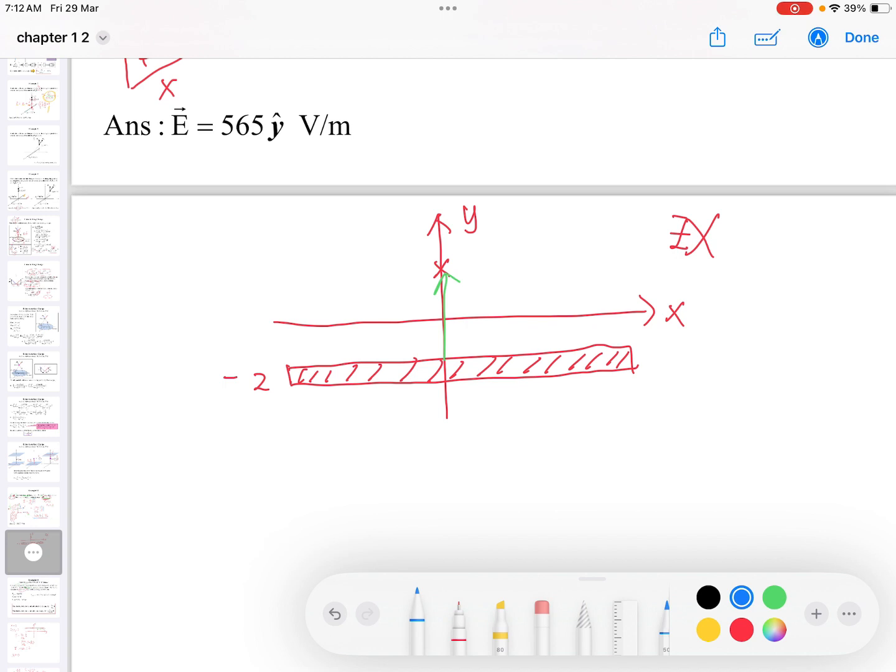Okay, the axis that you must draw is the axis that your plane is located at. So your plane is located at the y-axis. So you can draw the y-axis and locate your plane. This one is the side view of your plane. You are looking at the side view, because the plane is actually very big. So the other axis can be x or can be z.